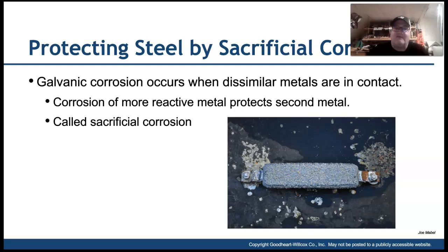We talked about galvanic corrosion before, so we will do a little bit of a lab on galvanic corrosion as well, so you can see and understand how we can use this idea of different reactive metals that are more reactive than others to basically become sacrificial parts. That way, especially in terms of washers, we want the washers to fail first before a bolt. That way we can maybe even see it and replace that before we have a catastrophic failure. So there is also a use here that's very, very important.